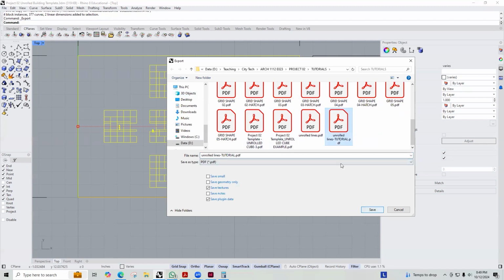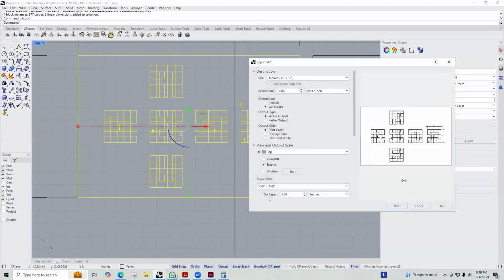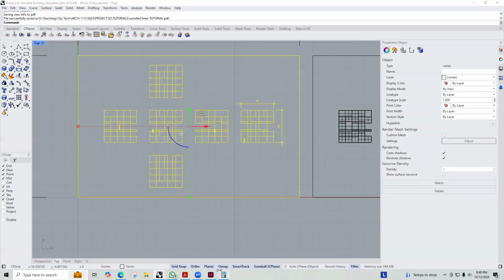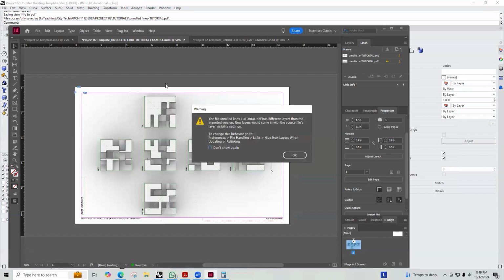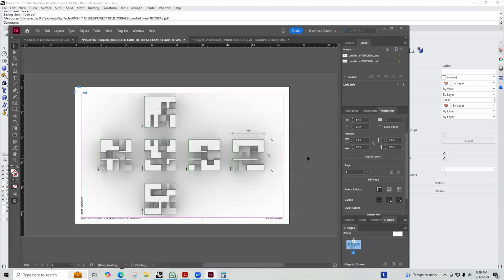and all you're going to do is click the same exact drawing. Make sure that you do not move the location or change the name. Click the same exact drawing, press Replace, allow these settings, and you'll see this little yellow triangle. That means that the link has changed. So I just clicked the little arrow to relink it. Okay. So now if I press Shift W to see the full view, you can see my little scale figures that are now propagating the building.